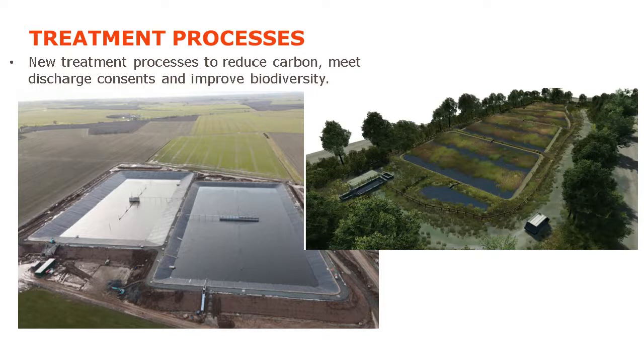The buildings on the left, you can just see, contain some upfront screening, and then it cascades through the wetland system. This is the size of, I think, 3 Olympic swimming pools. They're hoping with this system it will remove the phosphorus as per the discharge consent. It will boost local wildlife. It's a natural way to remove phosphorus. It's sustainable, and it's certainly a low carbon solution. But again, a lot of land is required to deliver this.